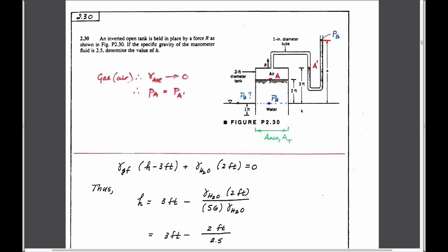So that's the outline for this. You notice that we have air in here, which was much lower density than the water that's in the cavity. The gauge fluid is different from the water, and so quite straightforwardly we can calculate what the pressure is in here, and that allows us to define the magnitude of the height of the particular column.